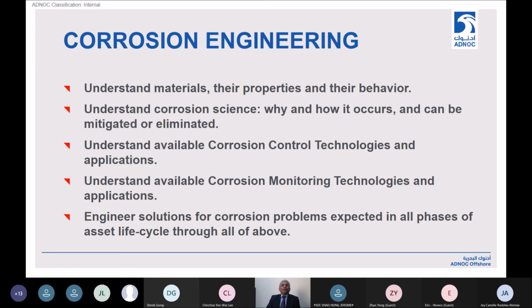Corrosion monitoring technologies: we normally rely on NDT as an inspection methodology, but today we are looking at proactive corrosion control, which means we have advanced non-destructive tools or in situ or intrusive corrosion monitoring devices installed in our systems, which tell us how our control is working. If there are deviations from the control criteria, we're able to take recourse as fast as we can in order to bring about important proactive corrosion control.